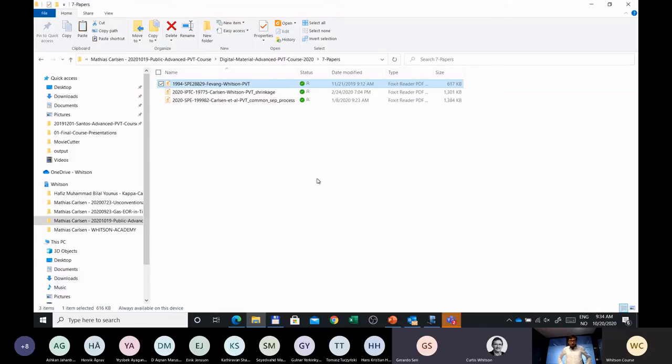The gas was essentially dry, but the small amount of liquids was going to be very important for designing pipelines. It's such a big field that they wanted the detailed small amounts of heavier components in the reservoir gas they would be producing, transporting and processing. So they tried to sample these early Troll field gas well tests using the Thornton isokinetic sampling.